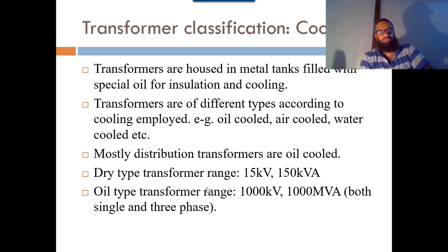So now the third important thing is cooling. If we talk about the transformer, when the current passes in the transformer it will heat up due to the current in the transformer, the coil will be heated up, and this coil, in order to reduce the burning effect, we usually use oil to absorb this heating, and this oil is used to transfer heat. We have cooling ducts, and these cooling ducts will remove the heat, and overall temperature will be maintained.